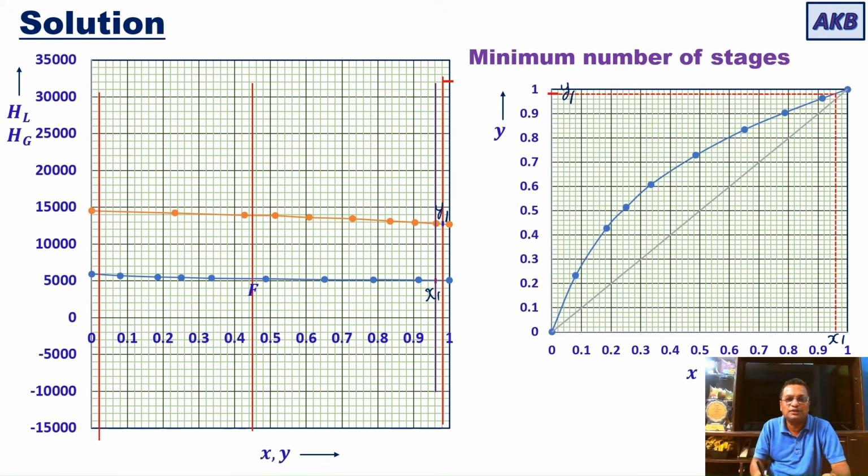So after drawing, because this line is going to meet delta D, which in this case is at an infinite distance when the column is operating under total reflux. So you get x1, y1, connect x1, y1 with the tie line as usual. So in the process, you get y2 over here. So let me just show, this is y2, which in this case is equal to 0.96. So again, we will locate y2 over here and get the corresponding x2 that is in equilibrium with y2.